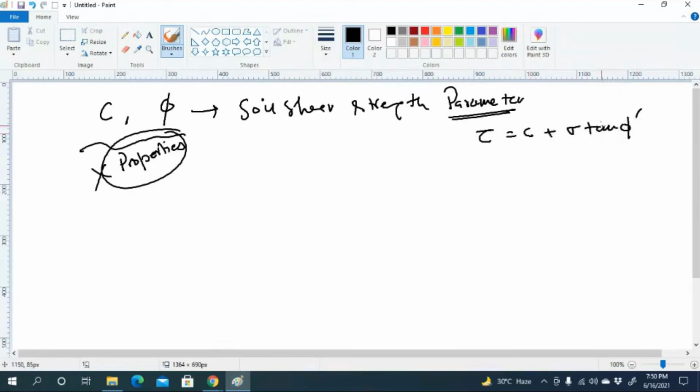and if we use this equation in terms of effective stress, we all know that we represent this with a dash, because C dash, and sigma dash is sigma minus u, which is total stress minus pore water pressure. Now, I'm just going to confuse you.